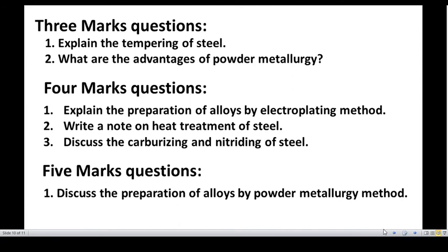At this temperature, what happens? When nitrogen is diffused into the base steel, the hardening of steel occurs without quenching of the surface. So this is about the nitriding process in the heat treatment of steel.